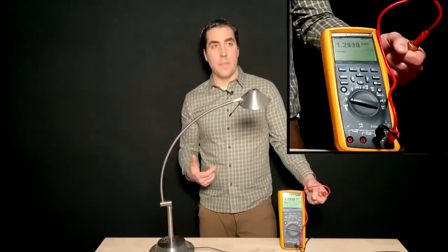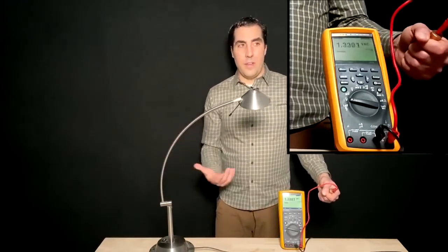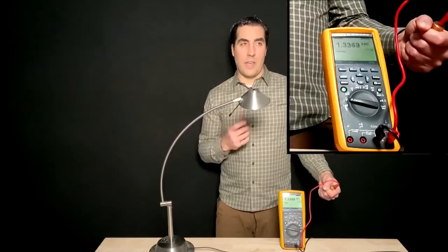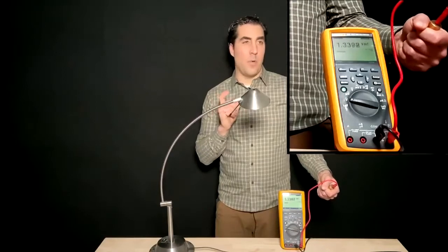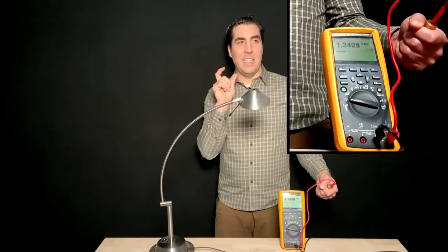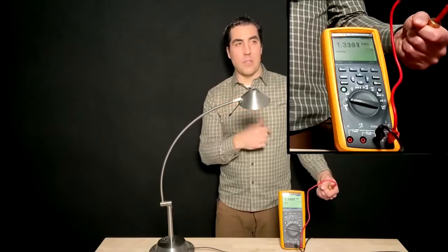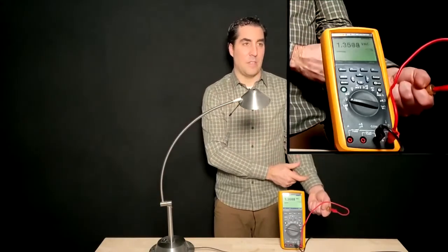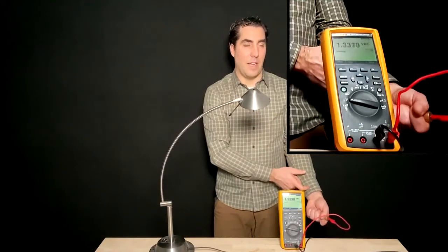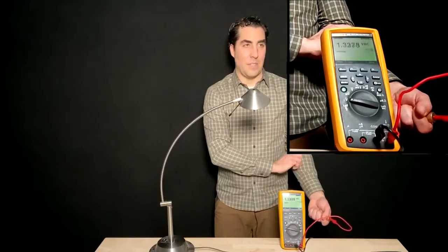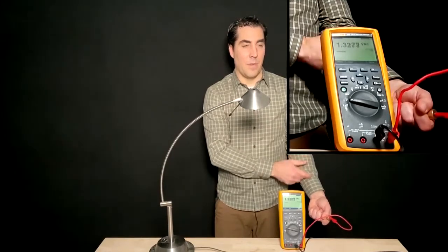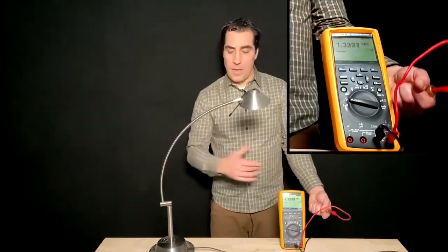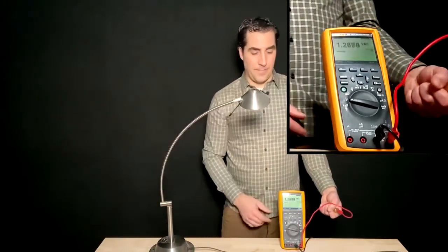And if we put that into perspective, that 1.3 volts right now is almost like having a AA battery. A AA battery would be 1.5 volts, but a AA battery is DC electricity. What we're talking about is alternating current electricity. So it's almost like taking a AA battery, connecting it to the surface of my skin, and flipping it from positive to negative 60 times a second. Okay? And that's AC electricity, and from the voltage or the electrical pressure.